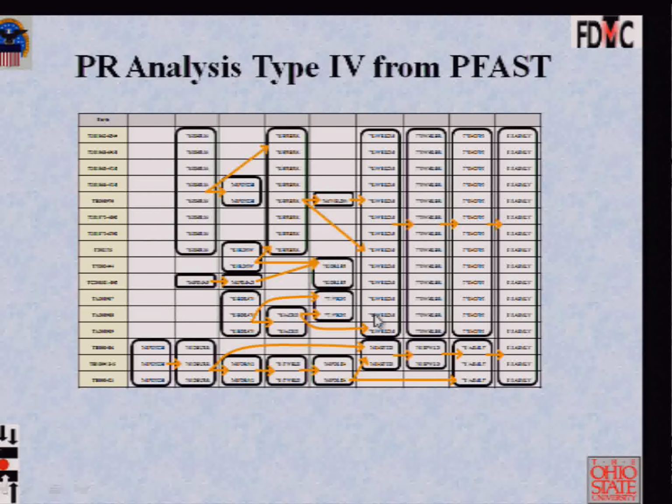So this is the whole idea of the point of use, that because this little matrix in Excel is a coming together of all the individual value streams logically, you're pretty much being told that as soon as things come into the MIG welder, you would like these work centers to be next to each other. Like this work center is spitting stuff out to the Viking as well as being sent directly to the MIG welder. So next to the MIG welder should be these 2 work centers, and whatever comes out goes into a holding zone where the MIG welder pulls those parts in and creates a sub-assembly. So look at all the welding points. There are 761 H stud, 764 weld M, 763 weld M, 761 assembly, 811 assembly.